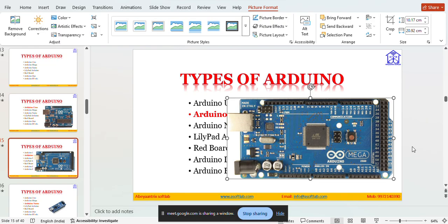If you require more digital and more analog pins, you can use the Arduino Mega board, to increase the number of devices. Let us say you are using the Arduino Uno and you have around 20 devices, like sensors, displays and output devices, to connect to the microcontroller.